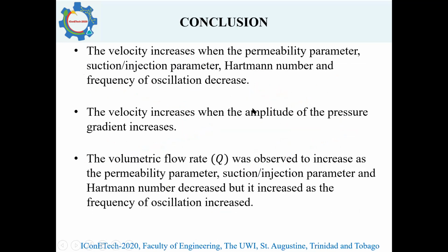In conclusion, the velocity increases when the permeability parameter, suction injection parameter, Hartmann number, and frequency of oscillation decrease. The velocity increases when the amplitude of the pressure gradient increases, and the volumetric flow rate Q was observed to increase as the permeability parameter, suction injection parameter, and Hartmann number decreased, but it increased as the frequency of oscillation increased.